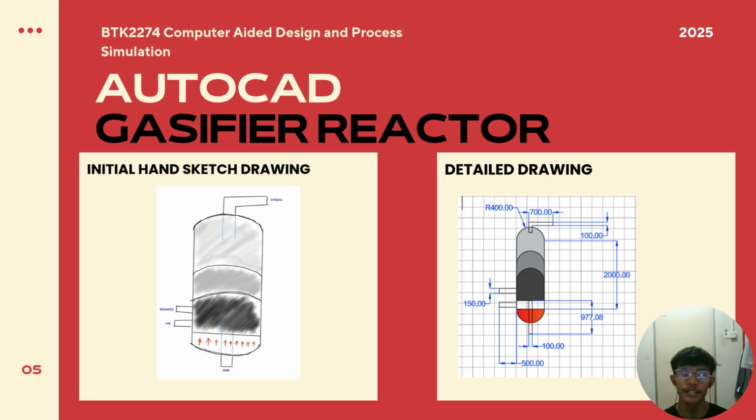A fluidized bed gasifier reactor used in biomass gasification is a system designed to convert solid biomass into a combustible gas called syngas. It achieves this by suspending the biomass particle in hot, inert bed material using an upward flow of gasifying agent like air or oxygen or a mixture.